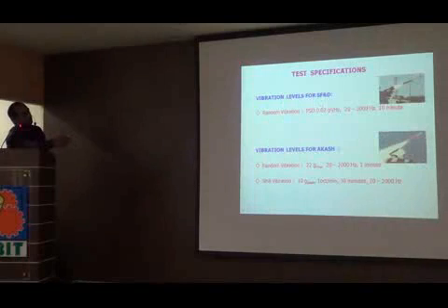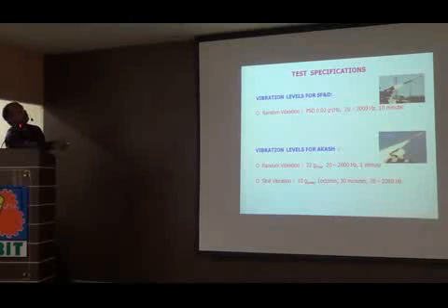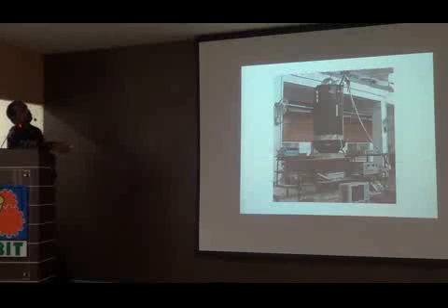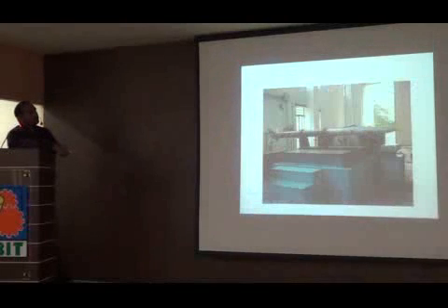To give you some idea about the test specifications, they differ; the Agni series, for example, will have 20 to 2000 Hz. The test specification may be 10 minutes, and the input level we call 0.02 G square per Hz. If it is Akash, it will be a 1 minute test, but at a very high level. It depends. The test duration will depend on the flight duration of the mission. Some can be 30 minutes if you want to see the endurance test, what we call. These are the different specifications.